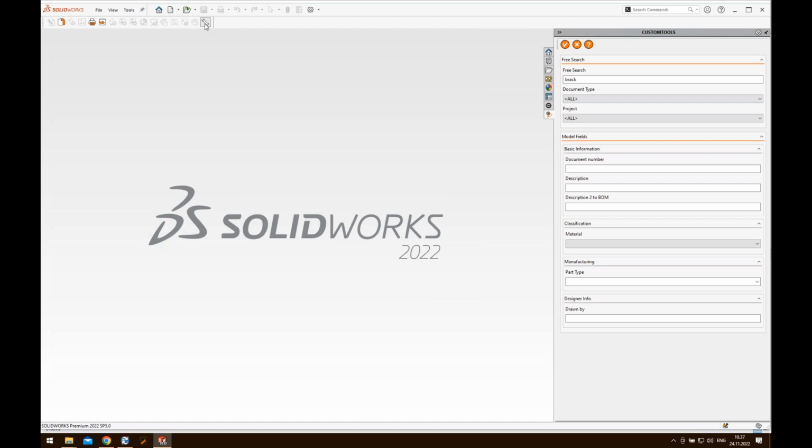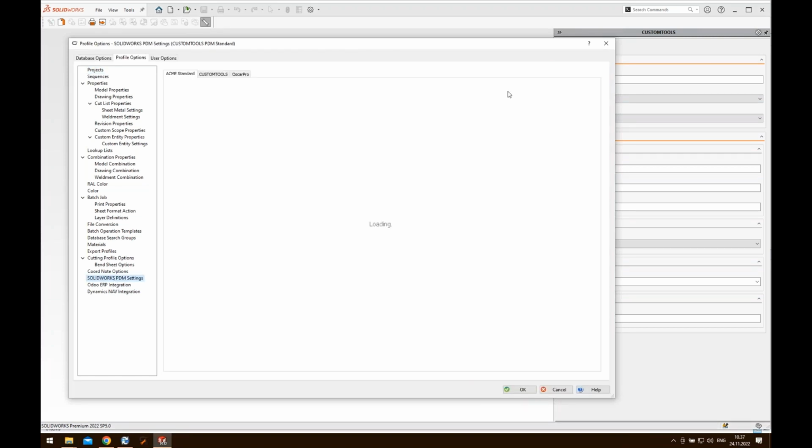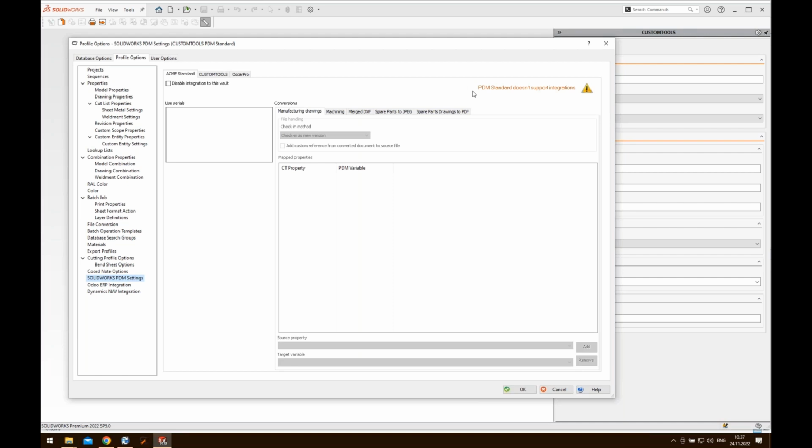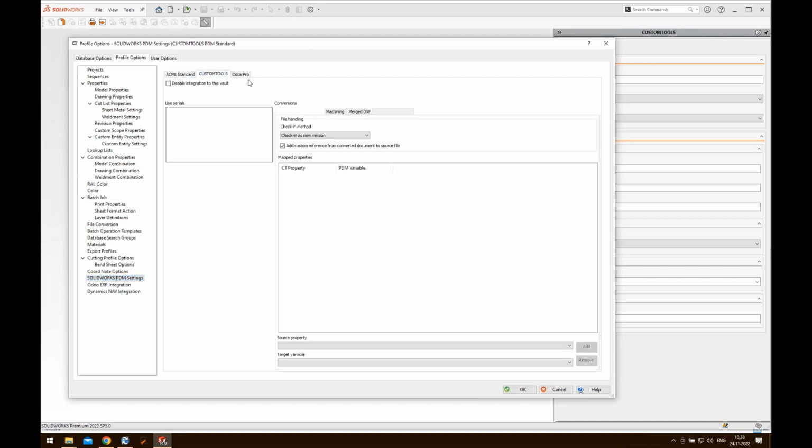If you would be using the PDM professional version, which was not the topic of this webinar, you would have integration, and then you don't have that problem. But here we see that PDM standard doesn't support integrations, so we really cannot use serials from the PDM, or take benefit of any of these integration features. And on the other hand, if we go to any of my professional vaults here, then we can adjust these options here.